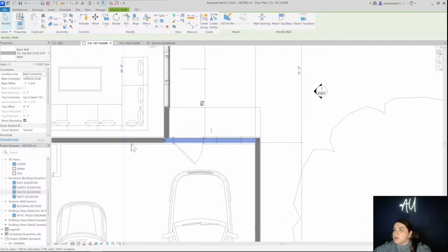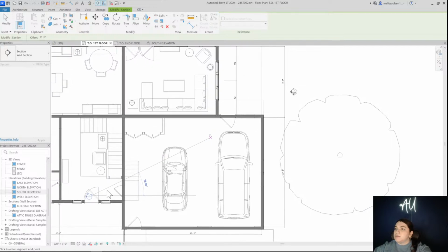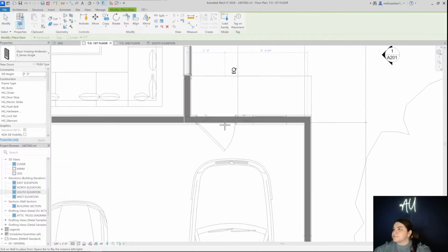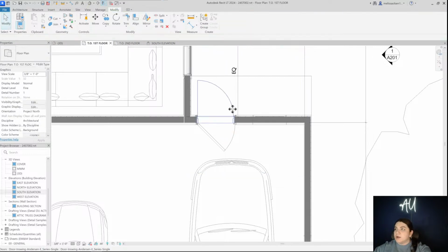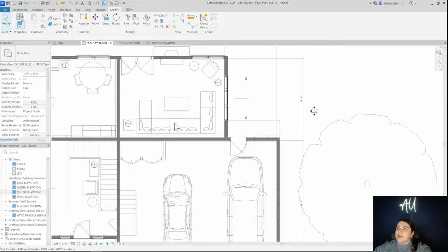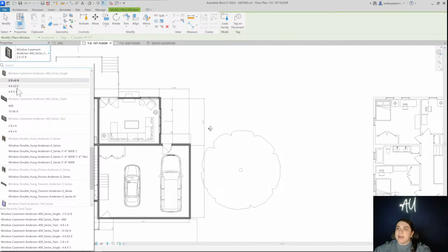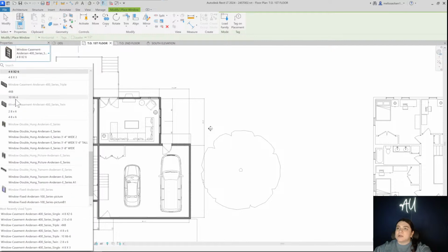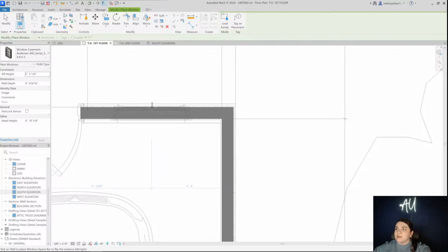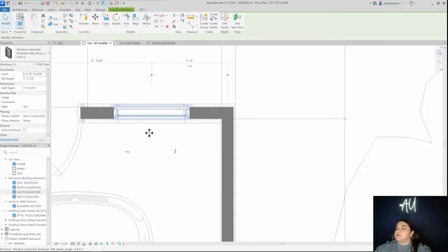And let's see what's working with this here. So we have another door. I'm going to create similar of the front door and put it here. We're also just going to put this lower because this is the garage, so we want to associate this to the garage slab. It's going to be a little bit lower in elevation. And we also need a single window. So I'm going to create similar from the single window over here, and I'm going to pick a bigger one than the one that's in the bathroom. And we're going to place that here as well. Flip that out so that the trim's on the outside.